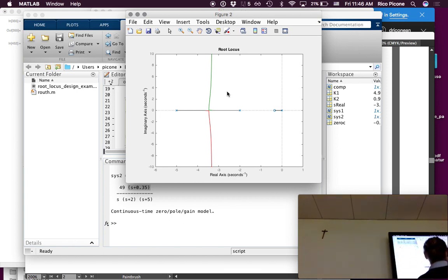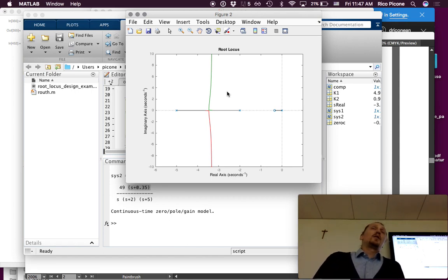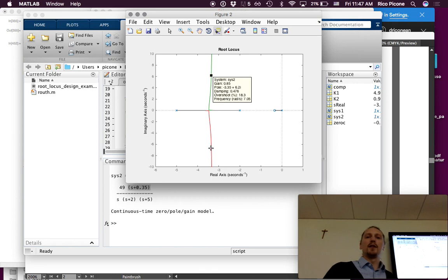We see that the root locus is pulled a little bit towards the origin, towards the imaginary axis, which corresponds to slower decays, right? So the settling time then is going to be longer, which it's not a lot, but it is a little bit longer. I mean, it's a very slight amount. So that may or may not be desirable, and we might need to move that 0 a little bit to fix that. But let's go forward with this. We didn't affect it too much. We affected it a little bit, but not too much. So let's find our 20% overshoot again.